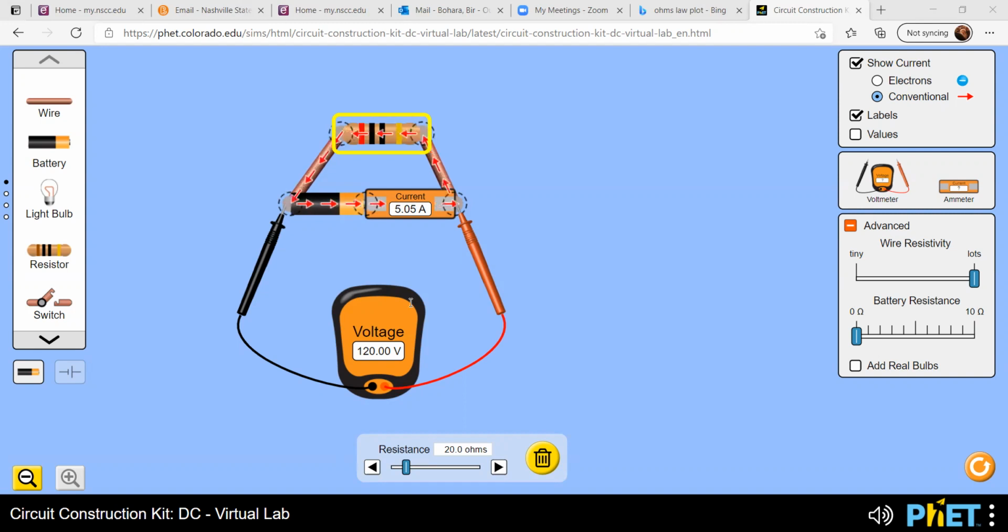So after completing this part, in second part, we are verifying Ohm's law. So your overall job is to plot IV curve. I is current, V is voltage. Okay. So let's go to the second part. Your circuit should look like this one. This is the rheostat having constant resistance, right? Not changing. And here is the ammeter, battery is here, and voltmeter.